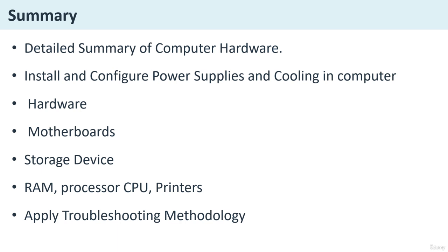Now, expansion slots and their uses. PCIe x16 is for graphics cards, which is for full bandwidth. PCIe x8 and x4 are for NVMe adapters, sound cards, or capture cards. Number 3 is PCI Legacy, that is an older standard, which is rarely used today.